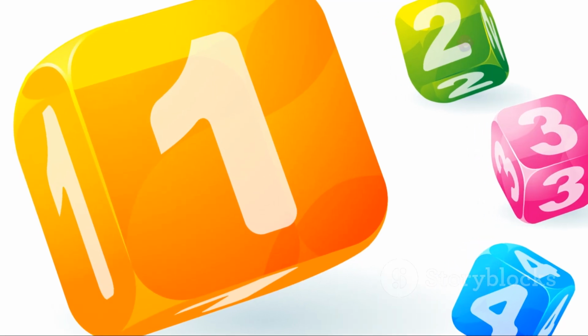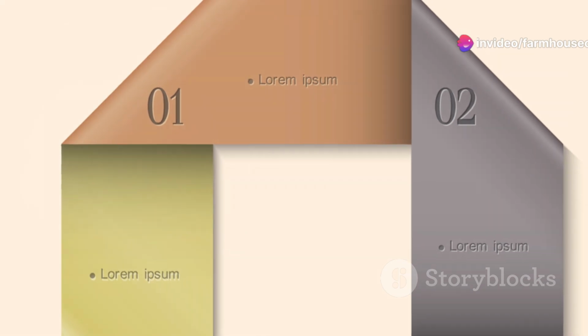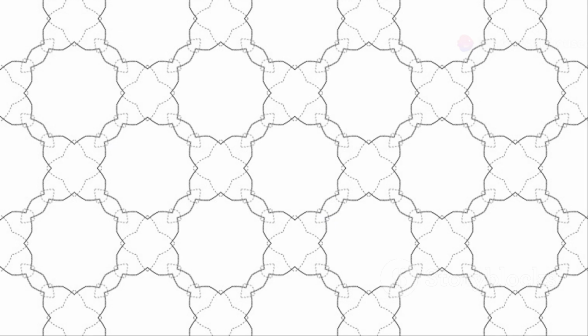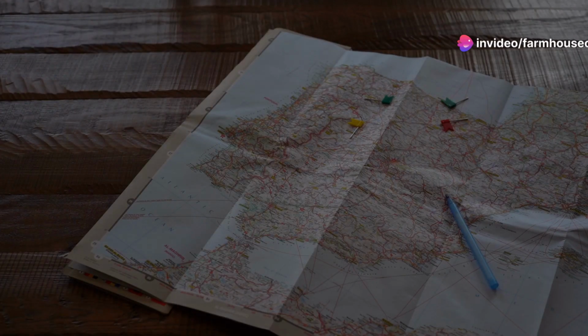A group should contain 2 to the power of n cells, where n is an integer like 1, 2, 4, 8, and so on. For instance, we can group 2, 4, or 8 adjacent ones. When grouping, we look for wraparound possibilities. Cells at the edges of the K-map are considered adjacent to cells on the opposite edge. This wrapping allows for more grouping options, further aiding simplification.